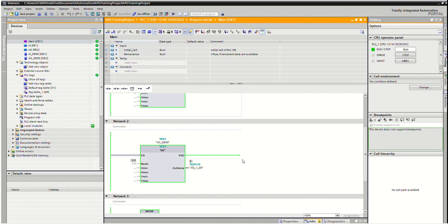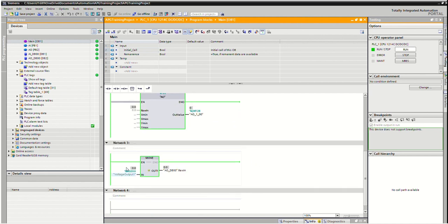See, our program is online. We can assign some voltage input. See, we assigned some voltage input to the voltage output that I'll directly assign to the output block, and that output block converted that voltage into 27640. It's a digital value. The voltage range is 0 to 10.